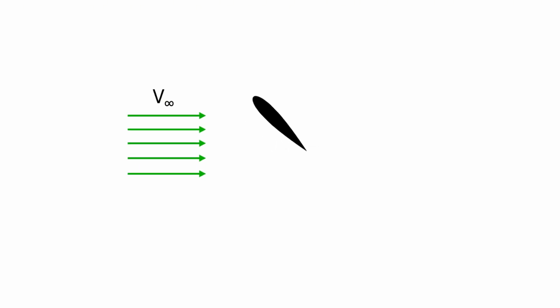When either the airfoil or inflow is unsteady, and when there are excursions of the angle of attack beyond the static stall angle, that's when the magic happens. That is, the airfoil does not immediately experience stall, and the lift magnitude continues to rise. Let's use the single-bladed Darrieus turbine as a way to explain what happens.